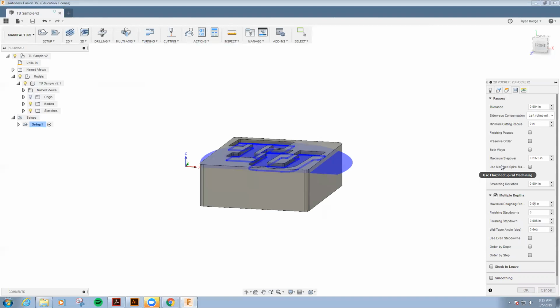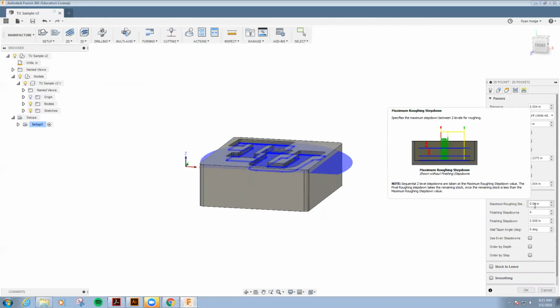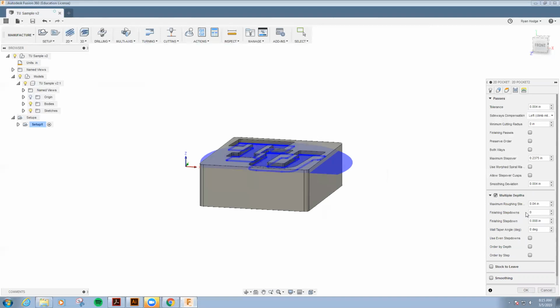The material is really soft. We probably would have no issue cutting the 0.1 depth that the letters are in one pass, but we'll just go with this default 0.04 for now. It'll allow us to correct things too if something goes wrong.